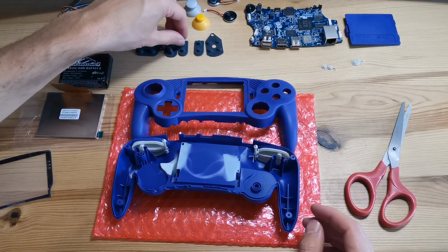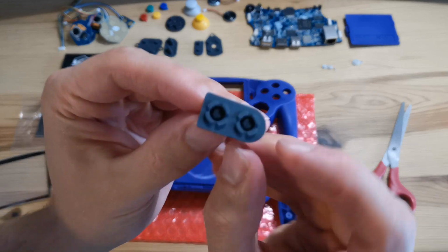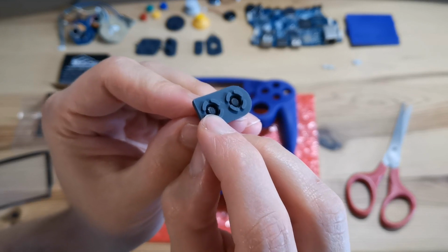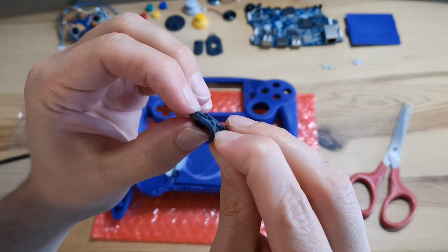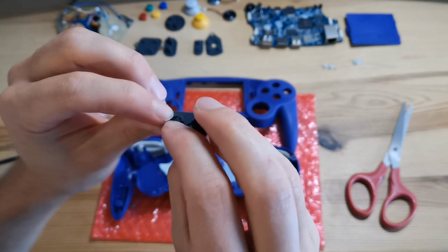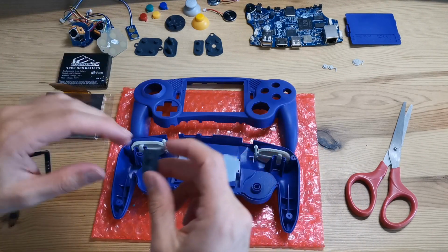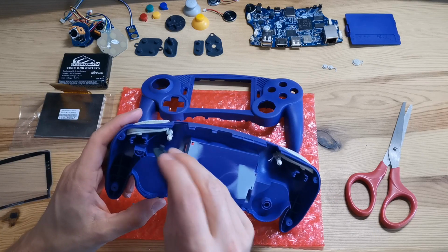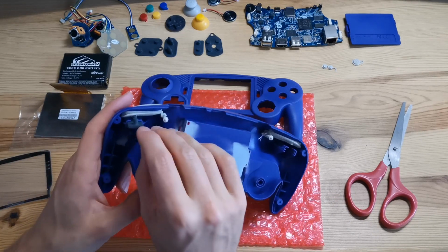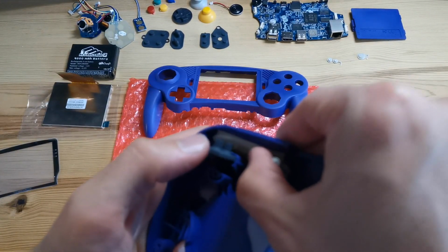So now we'll apply the silicones. Those are soft material, and you can see here the black part is actually a conductive material. So the idea is when you push the button, it presses here, and the conductive pad will make contact with the small PCBs here, and thus the CPU of the game console can register that you pressed the button. So we can just insert this here. You see this pillar shape, and see if we can insert it all the way down.